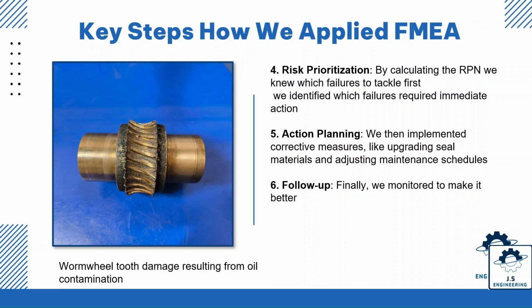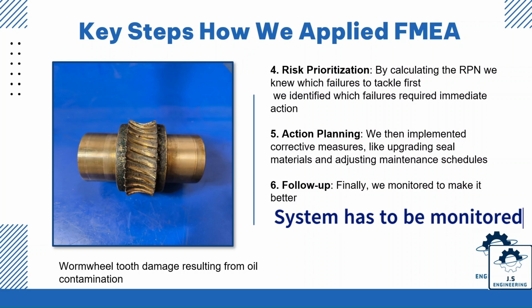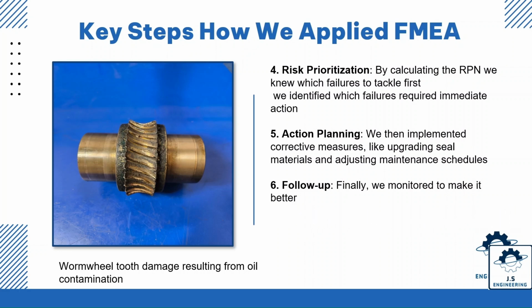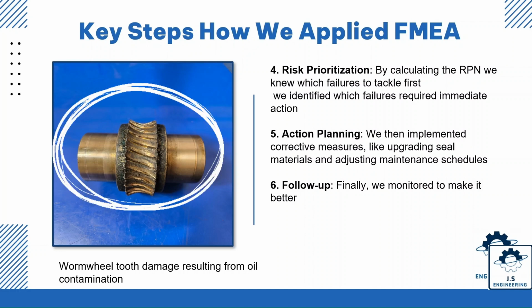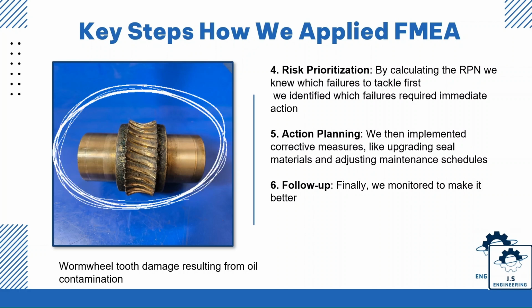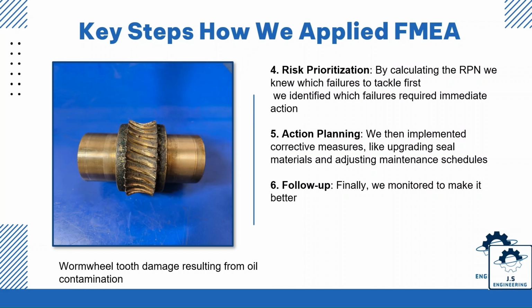And the last one is follow up. After implementing the fixes, we monitor the system to ensure the problem doesn't come back. A good example is a worm wheel in one of our machines. It had tooth damage caused by oil contamination. With FMEA, we identified the root cause, fixed it, and prevented it from happening again.